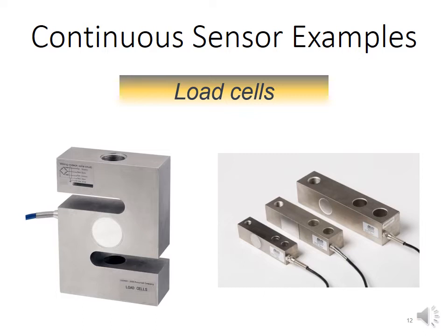They will be used to measure usually the weight of haulage trucks on entrance and exit, so as to tell maybe the material that would have been left into the company or the products that have been taken out of the company. Load cells also have got inbuilt signal conditioning. This makes them give an output in the standard range, that is 4 to 20 milliamps.